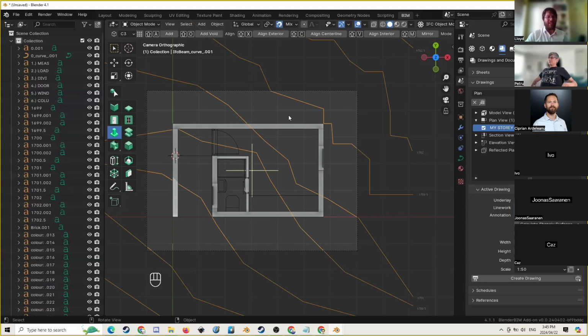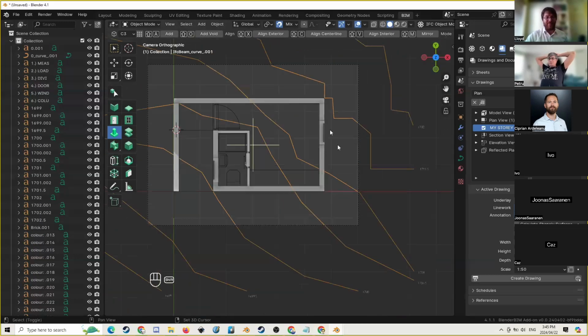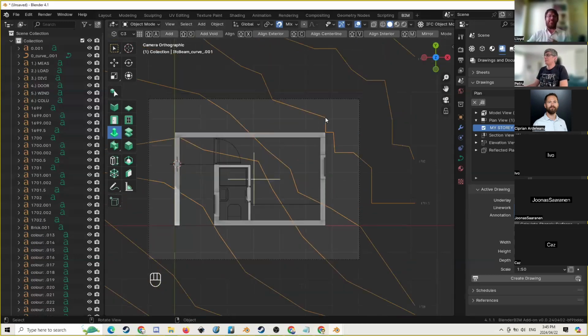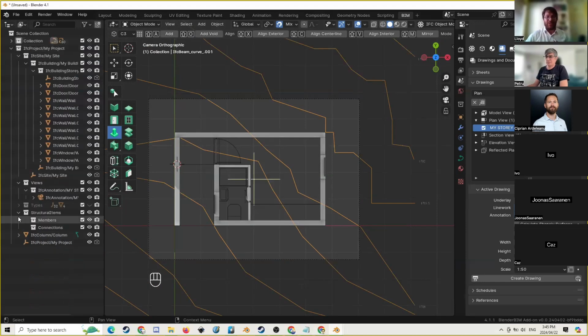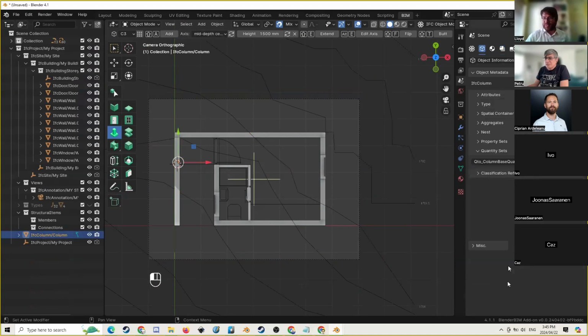The contours, I find project after project, especially when you're dealing with large sites. So I've got my fictional contours here. And essentially, I want to convert this into an IFC annotation. So in my column, I've accidentally put into the wrong space. I'm just going to spatially contain it so that it's correct with the IFC.